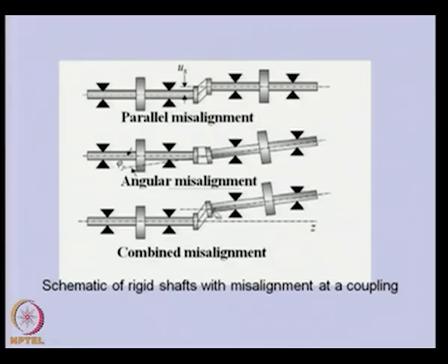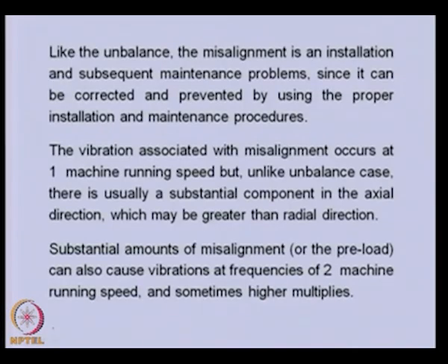So, we can expect that there will be large forces coming out of the bearing because of this misalignment, and that will reflect in the vibration signatures. Like the unbalance, the misalignment is an installation and subsequent maintenance problem, since it can be corrected and prevented by using the proper installation and maintenance procedures.